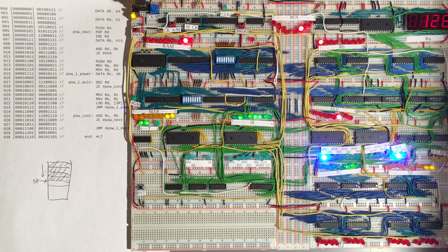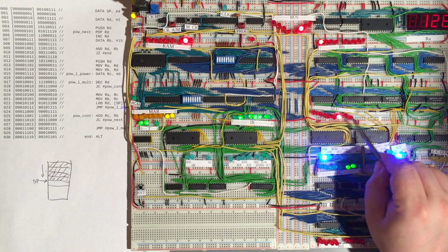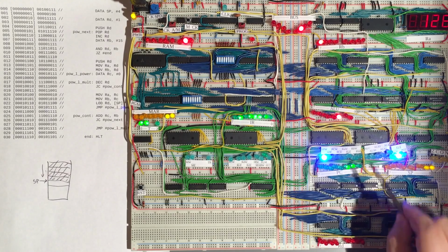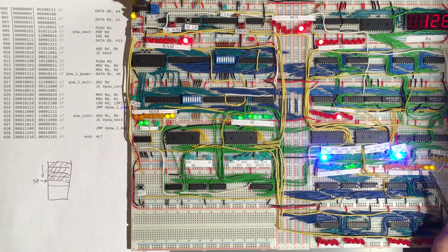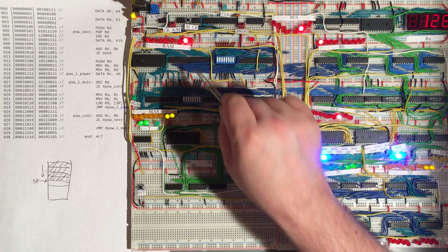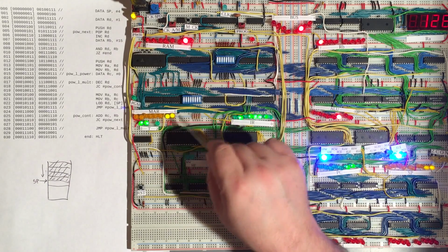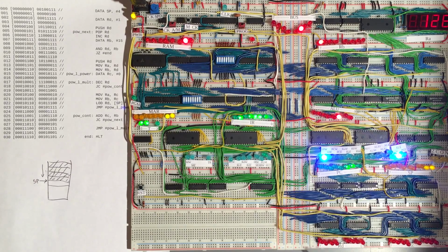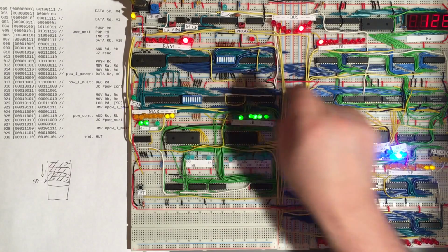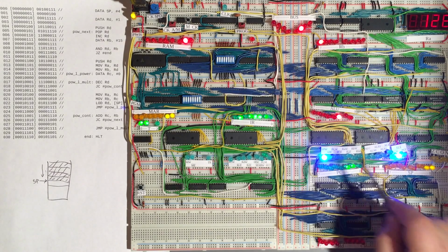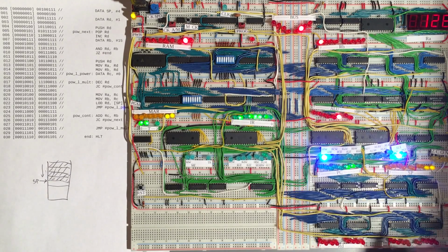So there it is. And so now we can do several things. We of course have this 4 here, and we need to get that 4 back into the stack pointer, because at the moment it's in this ALU register. But what we also need to do is to get the actual value, which is in memory, into the D register. And of course we only have one bus, so we need to choose whether we deal with this memory location first, or whether we deal with the stack pointer first. And that's sort of arbitrary, but in this case we've chosen to deal with the stack pointer first.